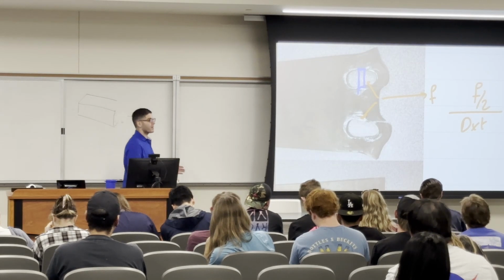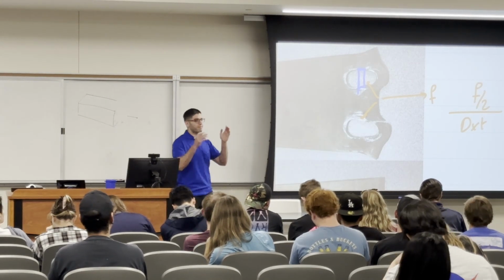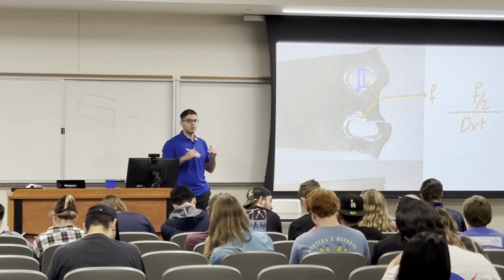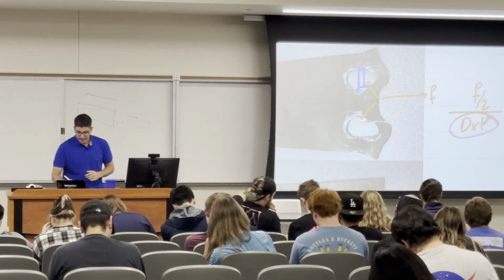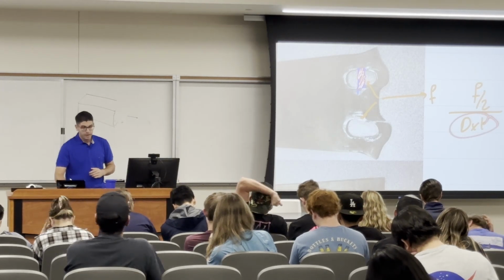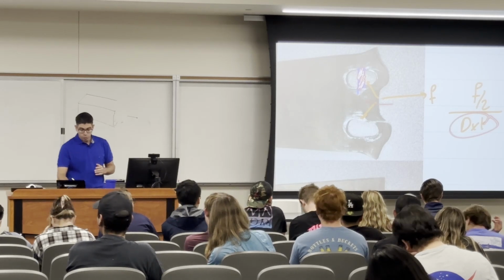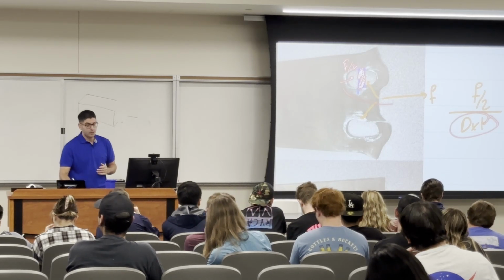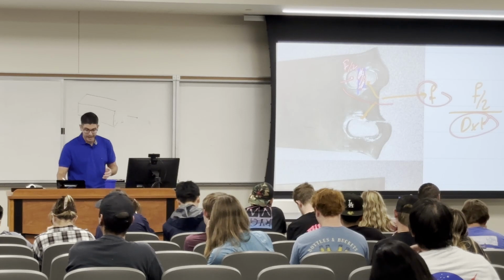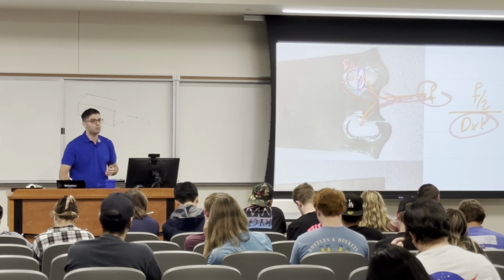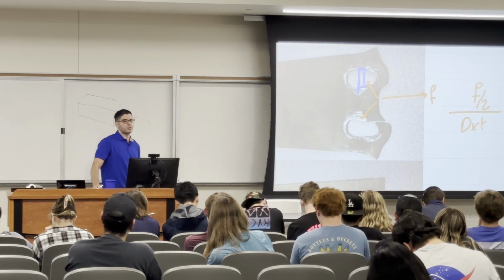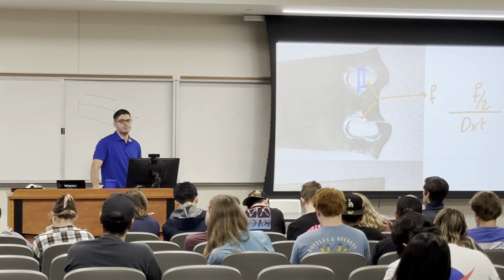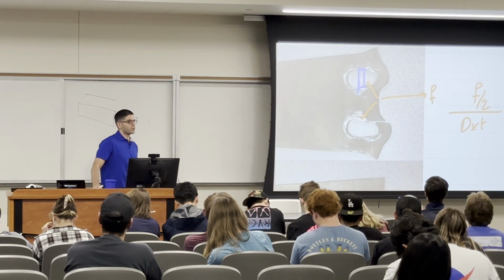And the same thing if I give you 4 holes, the force is going to be divided by 4, because DT is this area, and this area is subjected to F over 2. It's not subjected to the whole F, because the whole F, again, is passed through both of them. Is that clear? Any questions? All good?